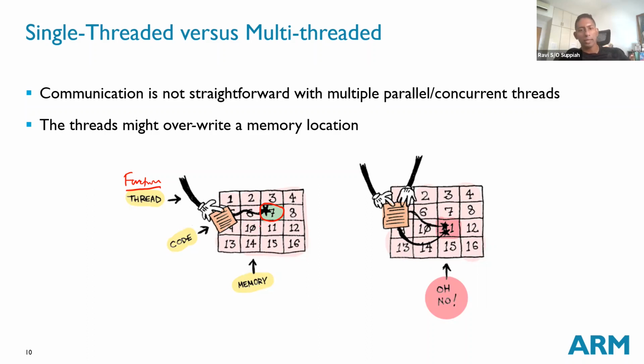But of course, in the embedded system context, you also have the other issue, which is the interrupt. If an interrupt also tries to access this variable, then you have an issue. But that is probably the only thing that you need to be careful about in a single-threaded environment: whether interrupts are also going to access the same variable that your main function is trying to access.